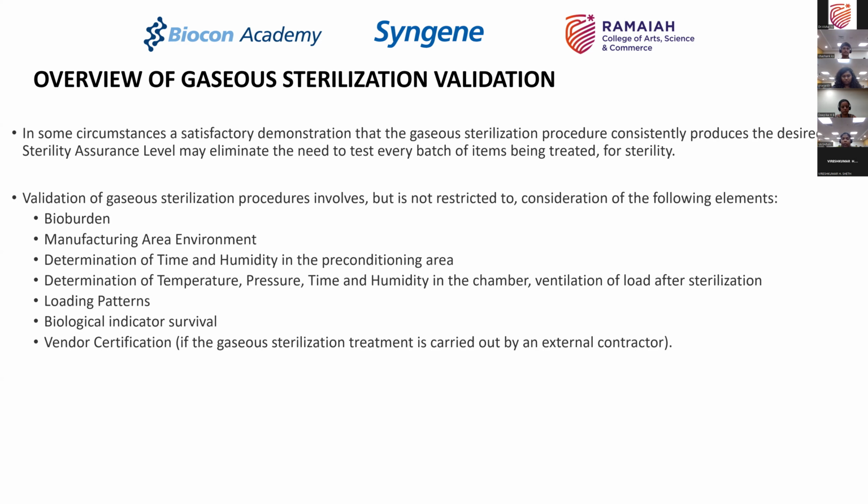Validation of gaseous sterilization process involves but is not restricted to the following. So, bioburden, manufacturing area environment, determination of time and humidity in preconditioning area, determination of temperature, pressure, time and humidity in the chamber, ventilation of the load after sterilization, loading patterns, biological indicator survivals, and vendor certification if gaseous sterilization treatment is carried out by external contractors.